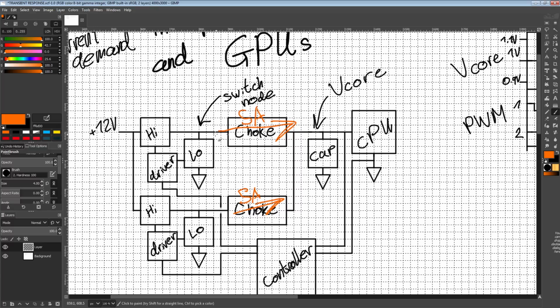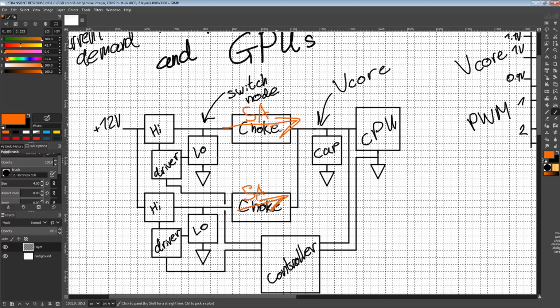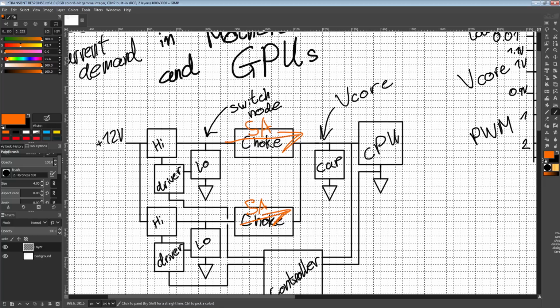So we have this 5 amps of current flowing through each of our inductors, and the way this current flows is it flows from our inductor into the CPU, through the ground plane, back through the low side MOSFET, and back into this inductor. And this 5 amps of current flow is entirely being produced by the magnetic field that we charged up in the inductor when the high side MOSFET was turned on.